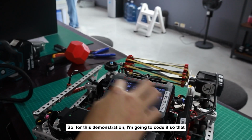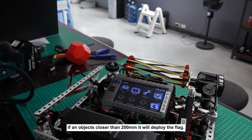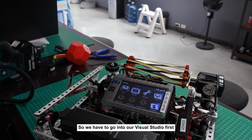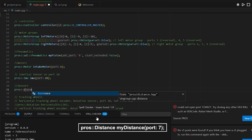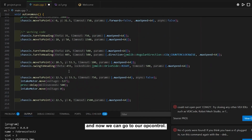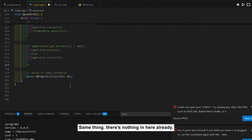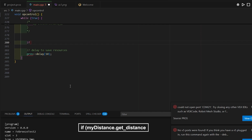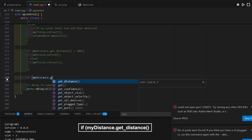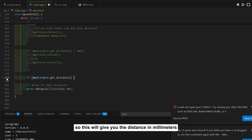So for this demonstration, I'm gonna code it so that if an object's closer than 200 millimeters, it'll deploy the flag. So we have to go into our Visual Studio first, and we can go to our sensors. So we need to add the distance sensor object. So pros distance, and then also my distance, and then it's on port 7, so I'm putting 7. And now we can go to our OP control. Same thing, there's nothing in here already. So I'm just gonna put a simple if statement, because we have a condition, which is if the object's closer than 200 millimeters. So if my distance .get distance, so this will give you the distance in millimeters,